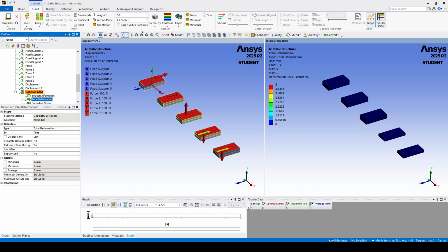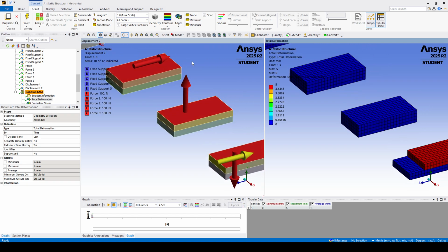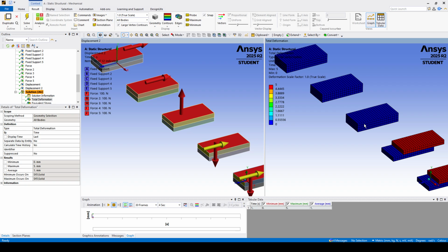As you can see on the model, even though we defined an upward force, the plate on the top is still sticking to this plate, because no separation means it cannot separate from the defined faces, but it can slide or move. Because here we didn't define any movement in any direction or force, it seems like it's still in place, but actually it can slide.